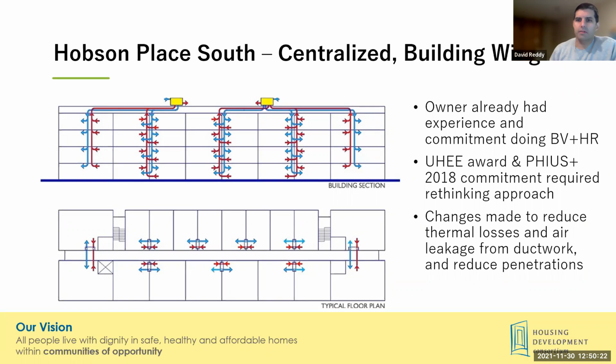at least longer than most developers, experience with already doing balanced ventilation with heat recovery. They built 2 buildings previously with the ERVs and all their new buildings are using balanced ventilation even before code was required. For Hobson Place South, the team pursued, relatively late in the design process, more like late SD, extra funding from the Housing Trust Fund called the UHE grant program, the Ultra High Energy Efficiency grant program, which came with a commitment to a PHIUS Plus 2018 or